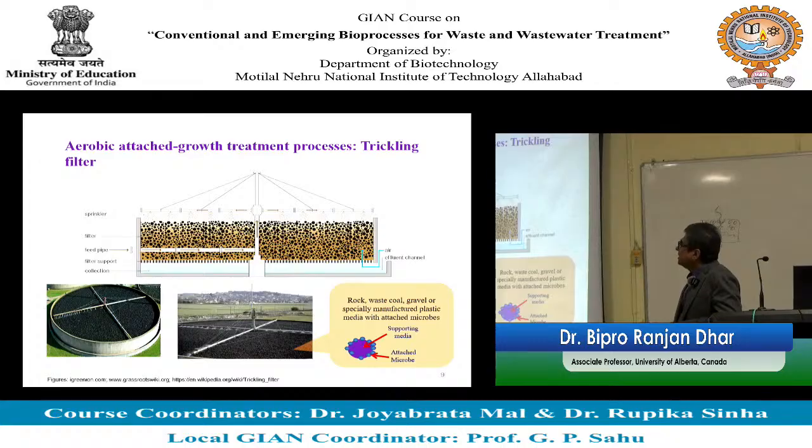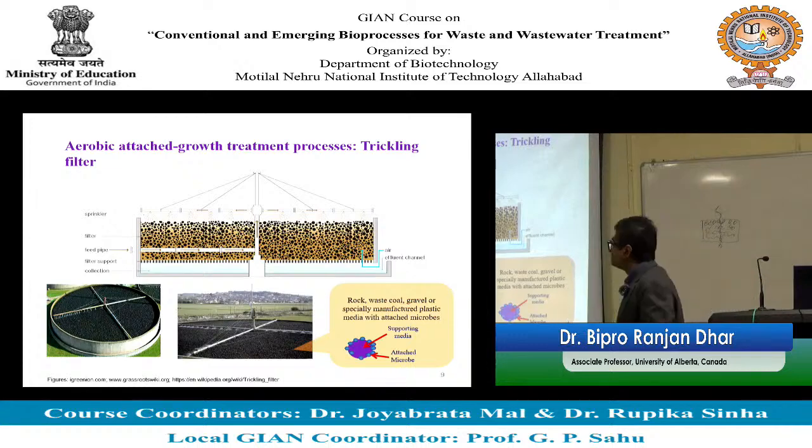Typically this kind of process can be feasible for small scale wastewater treatment plants for small communities. But one of the major challenges with this kind of system is that you have to have primary treatment. You have to remove all suspended solids, otherwise they are going to clog the trickling filter media. So yes, it is an attached growth process, but you have to have primary treatment prior to it.